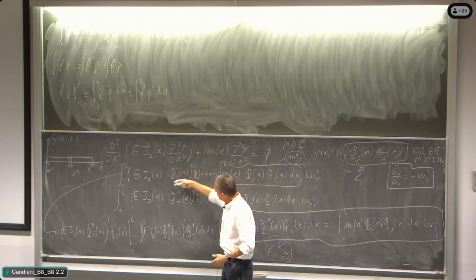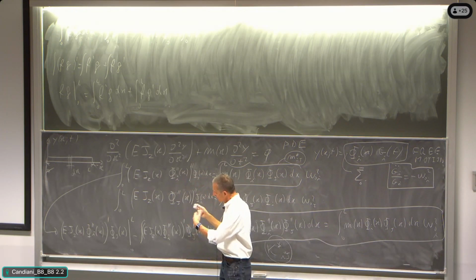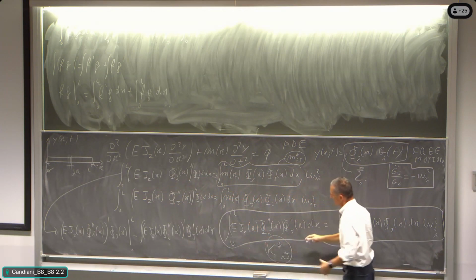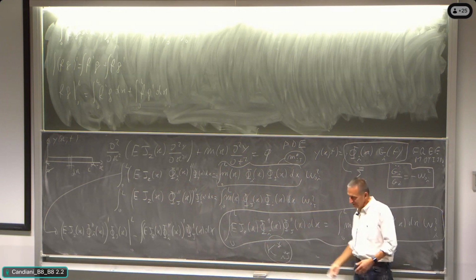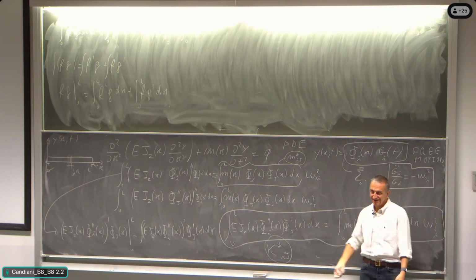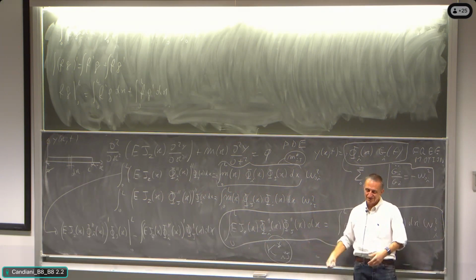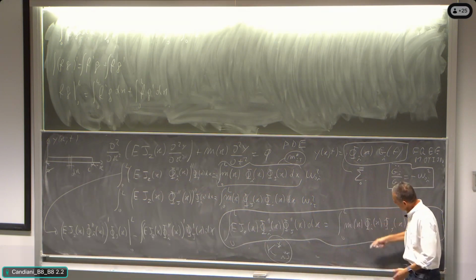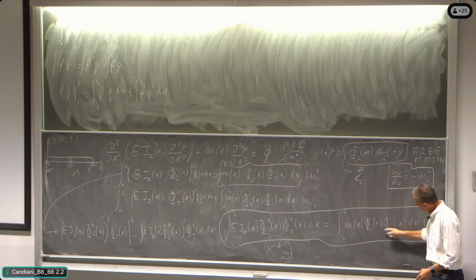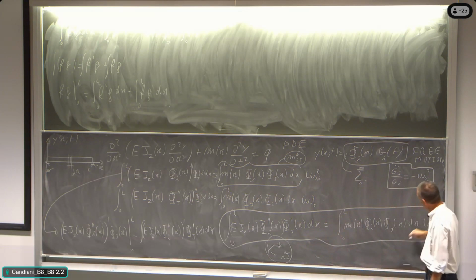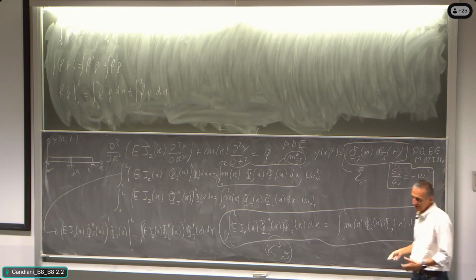And here, working with the derivation by parts, we are getting out some elements and finishing with the modal stiffness. And so we write modal stiffness equal to modal mass multiplied by omega_0i squared. And then we write the same modal stiffness equal to the same modal mass multiplied by omega_0j squared. The only possibility that all of that is working is that the modal mass or modal stiffness in the mixed term is null. So it is making all of that under the hypothesis that omega_0i and omega_0j are different.